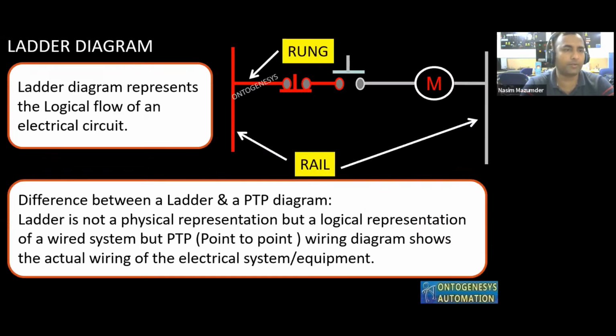Next one is your ladder diagram. Now, in case of your ladder diagram, this is not ladder logic. Don't mix up the two. The ladder logic that we use in case of our PLC, and the ladder diagram that we see in case of our electrical, are two different drawings. Exactly from this electrical ladder diagram, the concept of PLC or ladder logic came. What the ladder diagram represents is the logical flow of the electrical circuit.